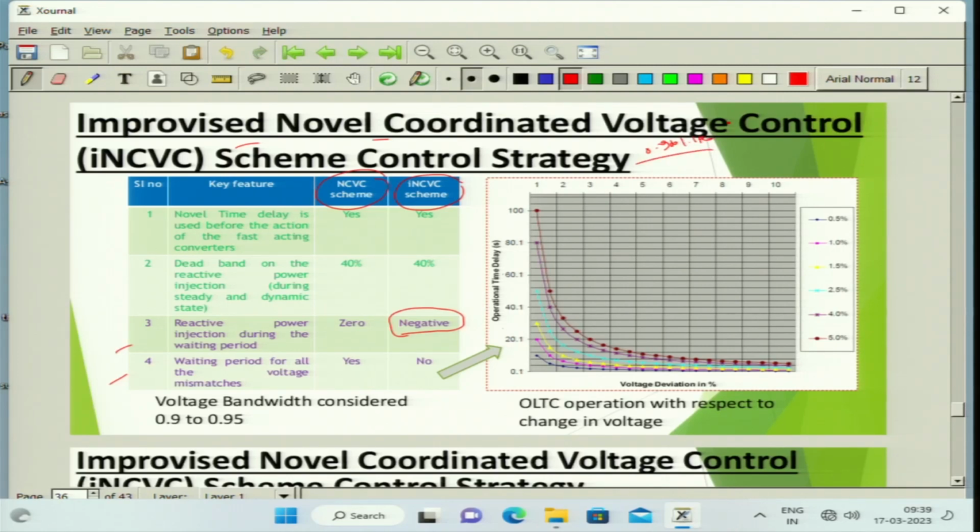So we are not taking the system away from the steady state or dynamic state. This is the time where we can have more reactive power reserve. That means we are taking advantage of the 4-quadrant operation of the inverter: they can inject reactive power, and they can also absorb reactive power. So, the system is in steady state, can we have more reactive power reserve? We have absorbed reactive power from the system.